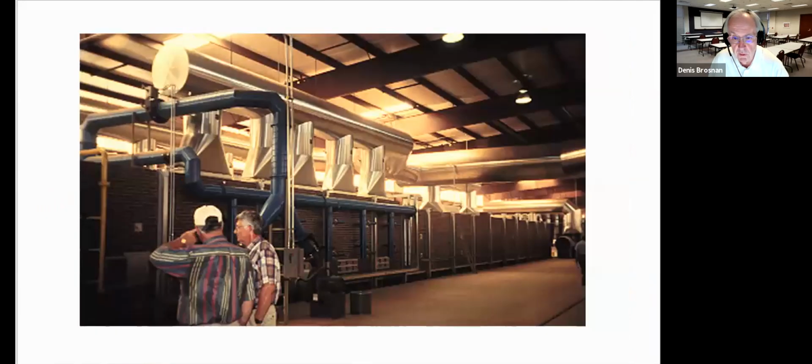This is a tunnel kiln. This is the quick cool section. So the product is coming from the left through the hot zone of the kiln. I can see a gas line going down the side of the kiln, and we're blowing air into the kiln to cool off the load right now. So railroad cars, or kiln cars as they are called, stacked with product, come in and travel through the hot zone of the furnace in this area, and then come through a quick cooling section as the product exits to the left. A continuous kiln.